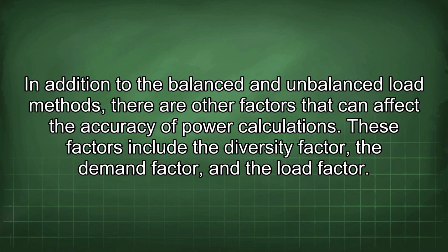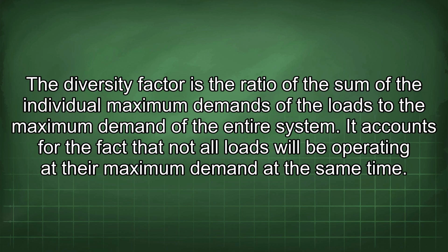In addition to the balanced and unbalanced load methods, there are other factors that can affect the accuracy of power calculations. These factors include the diversity factor, the demand factor, and the load factor. The diversity factor is the ratio of the sum of the individual maximum demands of the loads to the maximum demand of the entire system. It accounts for the fact that not all loads will be operating at their maximum demand at the same time.